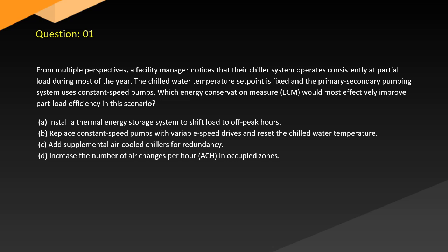A. Install a thermal energy storage system to shift load to off-peak hours. B. Replace constant speed pumps with variable speed drives and reset the chilled water temperature. C. Add supplemental air-cooled chillers for redundancy. D. Increase the number of air changes per hour in occupied zones.